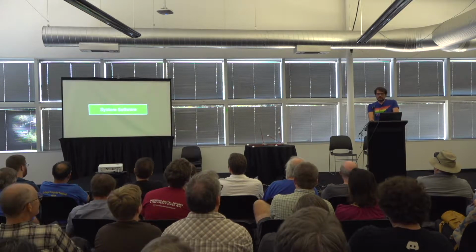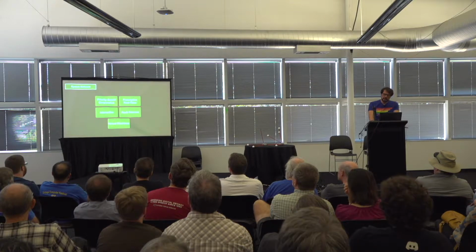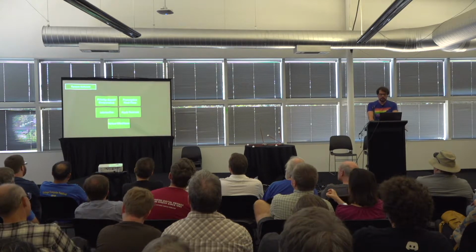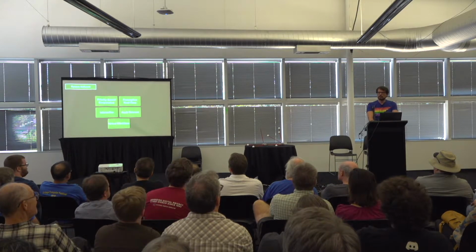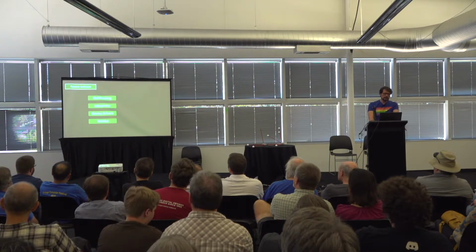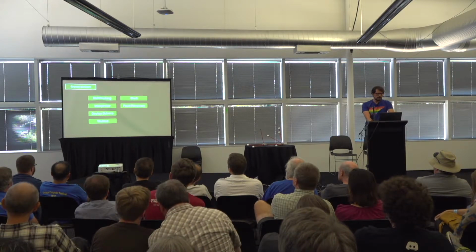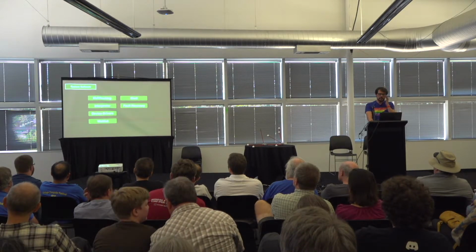The AGC's system software makes it a priority-based, cooperative, but also preemptive, real-time, interactive, fault-tolerant computer with virtual machine support. The topics we'll talk about are multitasking, the interpreter, device drivers, and the so-called waitlist, as well as the user interface and mechanisms for fault recovery.